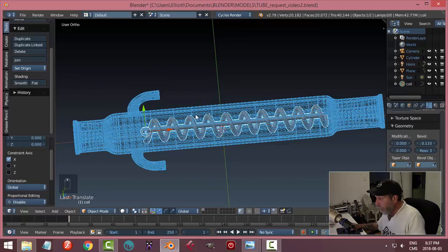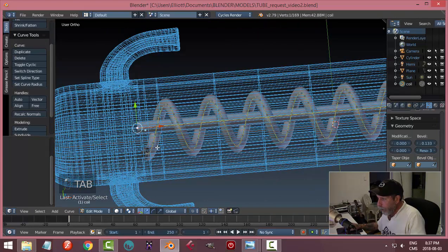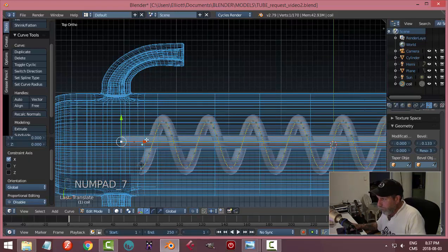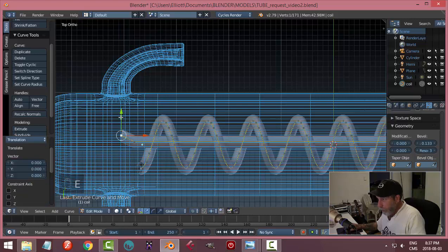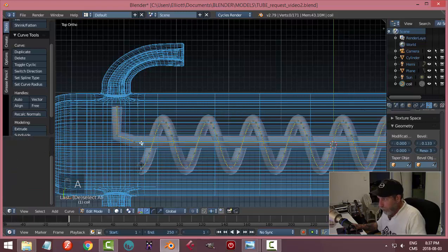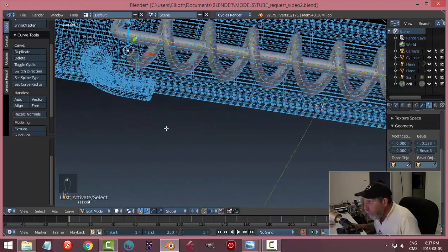We'll do that. Okay, in edit mode, I'll select that point, and I'm going to hit E to extrude, bring it up a bit more. Let's do this in top view. I'll bring it over a little. E to extrude, and I'm going to pull it over here. Grab both of those points, and I'll sort of center that up a little bit. Grab this point, pull it here. We get a bit more of a curve. All right. This point, yep.